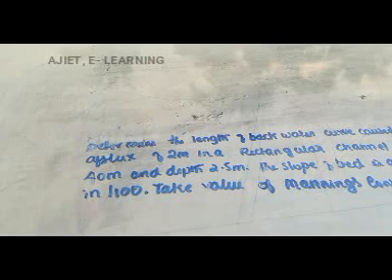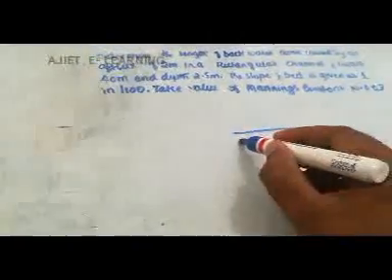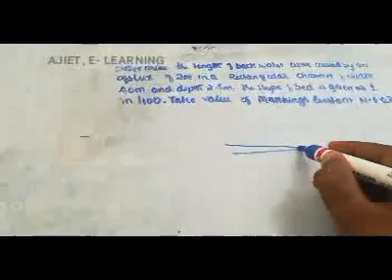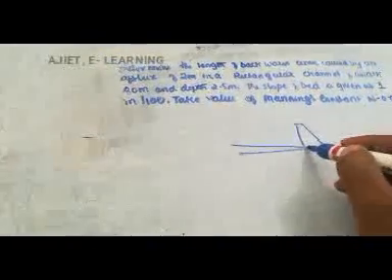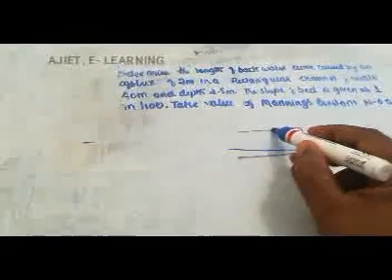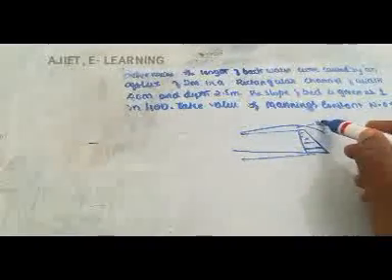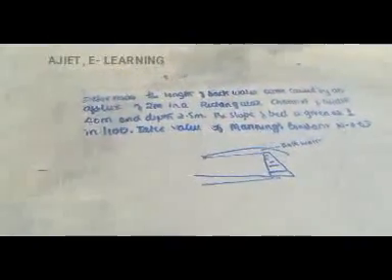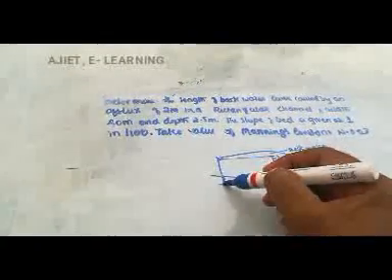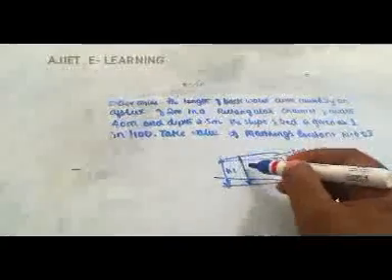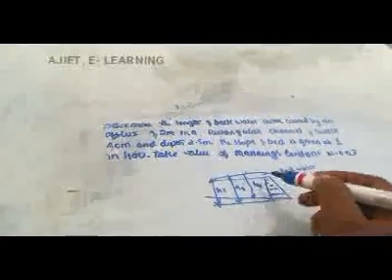Here, before we start, we need to discuss what a backwater curve is. Backwater means the water is flowing, this is the bed of the canal, and this is the surface, and here we construct a dam. The water flows from here, gradually increasing in depth as it approaches the dam. The profile created from here to here is called backwater. Gradually increasing water is called backwater flow. The depth gradually increases: h1, h2, h3, h4, h5, like that.